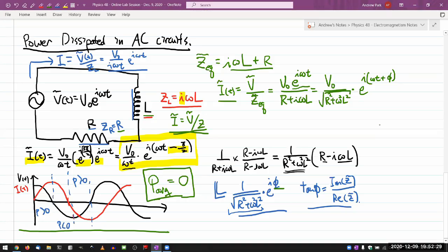So that's the expression for current as a function of time, and in some sense, there's nothing simpler. It's kind of the same thing I would have done if this were a resistor instead of an inductor. The only additional complication I had to go through dealt with a complex number, which is the price we pay for this being such a simple thing to analyze when you use complex exponentials and complex impedances.